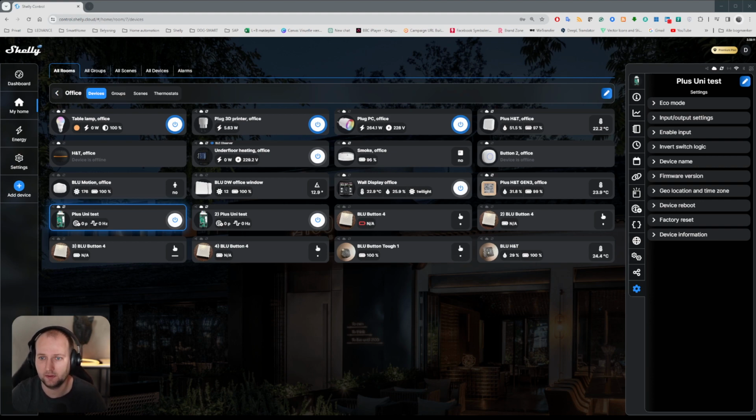Yeah, all right. That's a question about the dimmer. 10 to 240 watt dimmer. If you dim less than 10 watt, would you need a Shelly bypass? No, typically. I mean, it's very difficult with dimming. I have a lot of light bulbs that are less than 10 watt, and it works perfectly. But it's a matter of the quality of the light bulb.